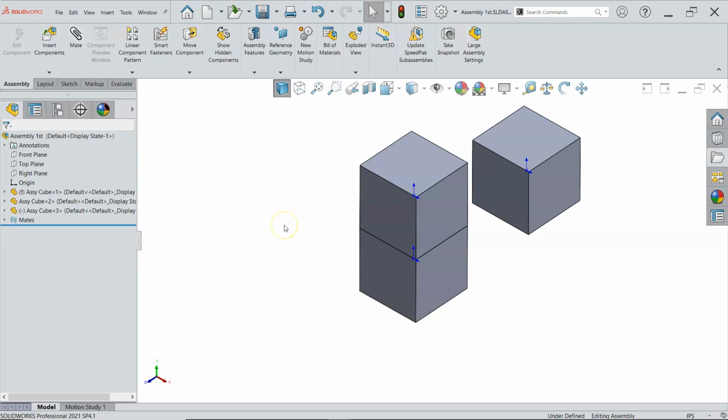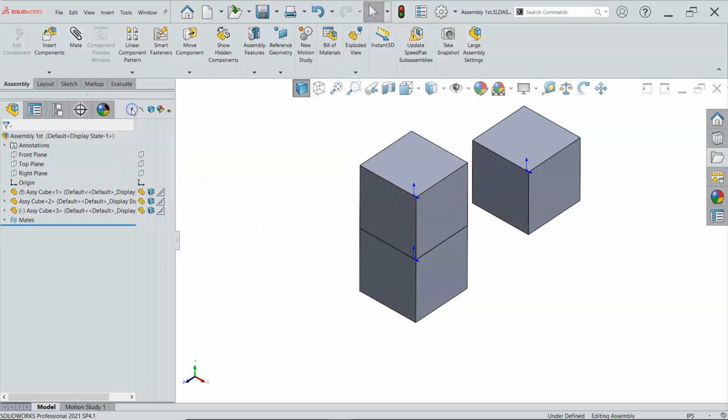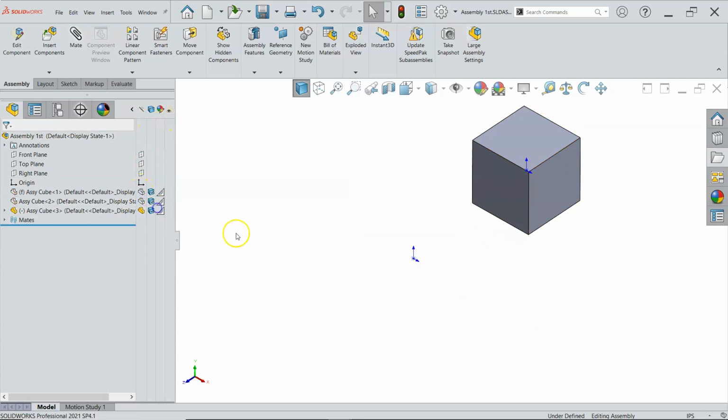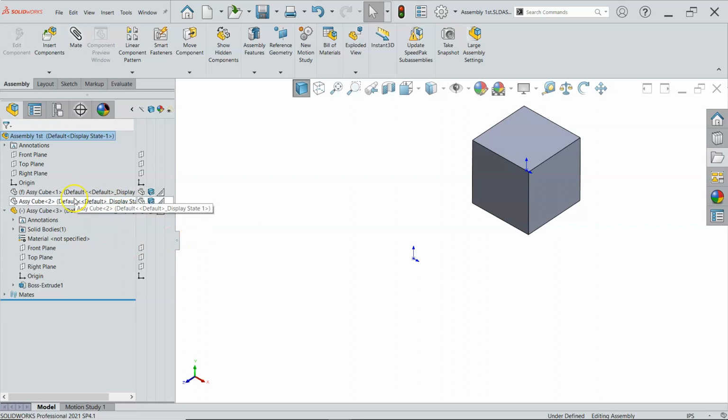into the geometry or into the assembly work area. Let's see, we did not use the plane, so I'm going to expand this out, and the first column over here on the view is that I can hide those objects. Right, so we did face-to-face coincident on all of the first 2 cubes. The first one was fixed. Second one came in and aligned to the faces. We can also use the planes. I showed that the front plane was aligned to the front plane.